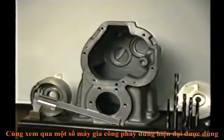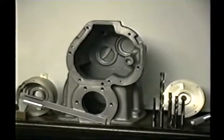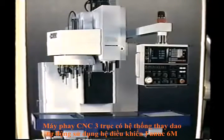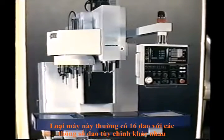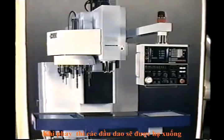And let's take a look and see what a machine like that would look like. This would be a typical modern vertical machining center today. This is a machine very similar to the machine that made the actual parts you just saw. It's a 3-axis machining center with tool changer. It has a Fanuc 6M control. This particular machine has 16 tools that would be changed by specifying the proper tool number. This machine is also capable of doing thread milling.